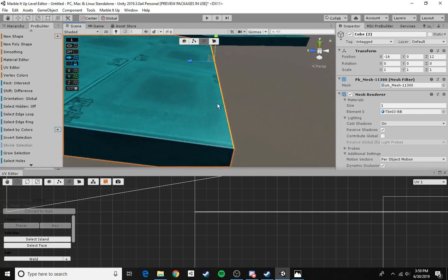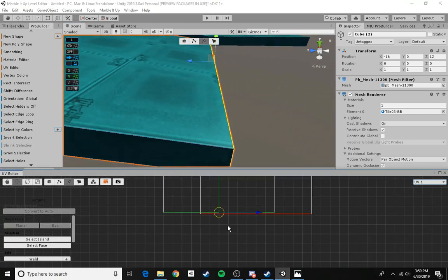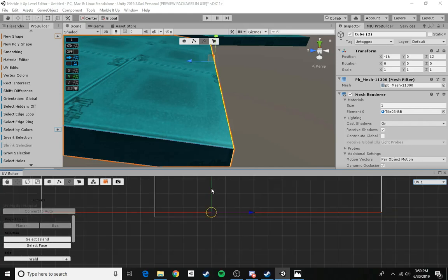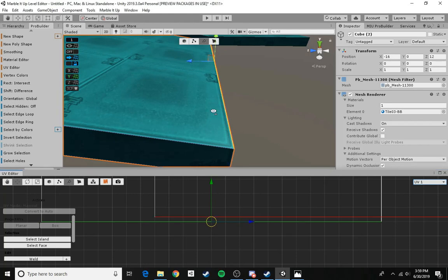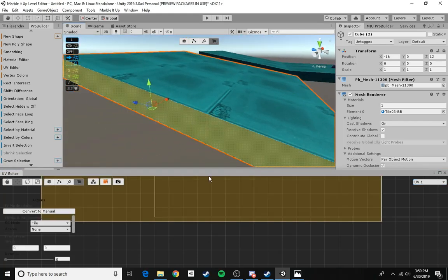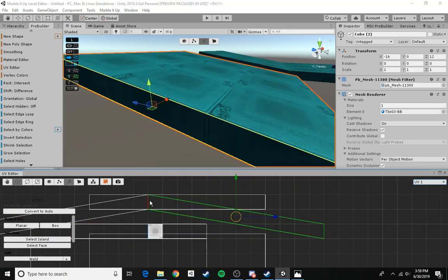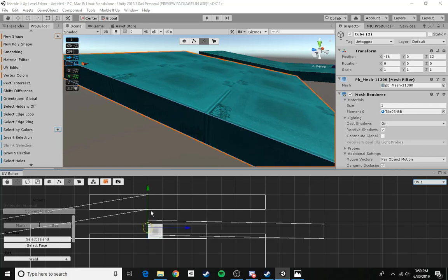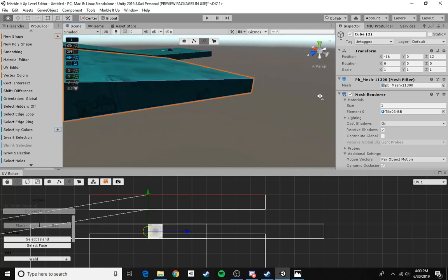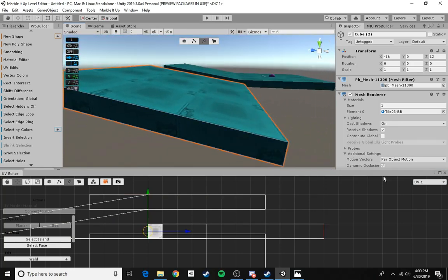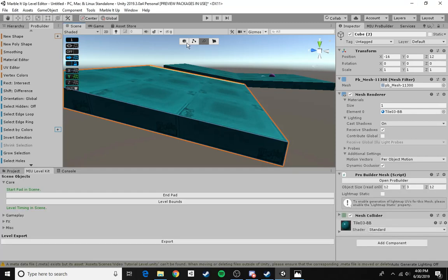If we go select the other face, you'll move this, and I am snapping to grid, so I'm holding control while I'm moving it. If we select one of these faces, you'll see that it's kind of slanted. So what we'll do is we'll take this edge, we'll move it down so that it's a rectangle again. Now you can see it's on the grid, and that looks better. But I'm not going to finish that. You see where that could get tedious. I'm going to move it back down.